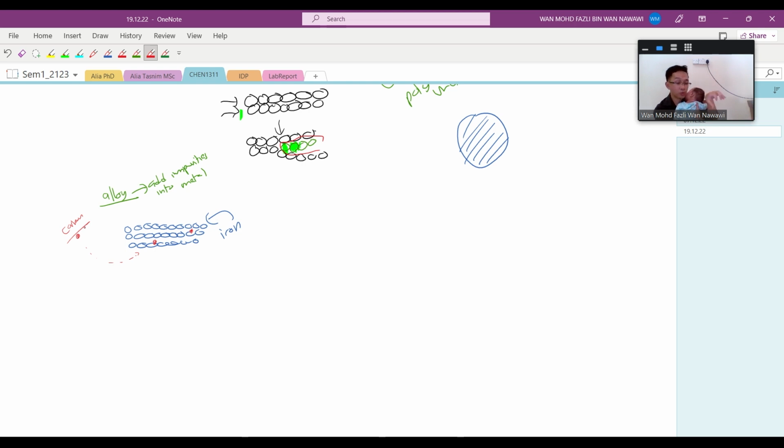When you put carbon inside iron, it makes the iron stronger, because when something is soft, we don't call it strong. If you want to use iron as a structural material, for example to make a bridge where cars can go, pure iron would become so ductile and soft that the bridge would collapse. When you put in the carbon, this ductility is hampered, and the product, which we call steel, becomes stronger.